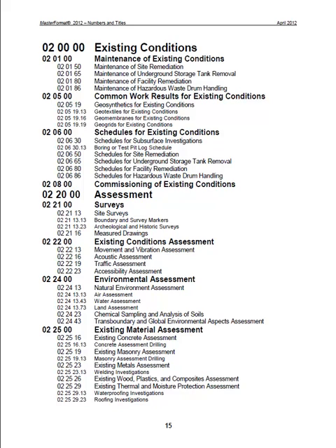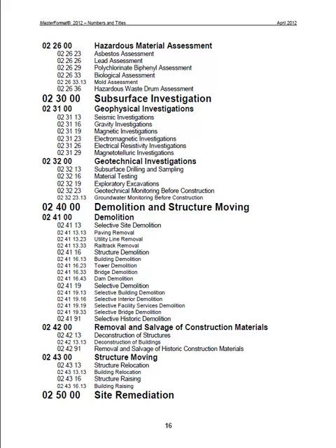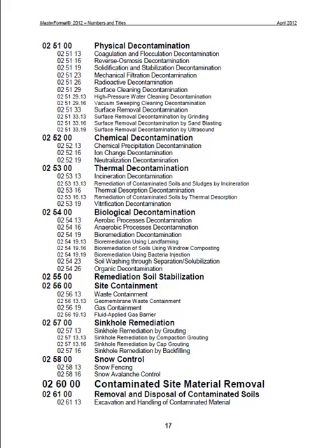Here's our Section 2, which is existing conditions. You see we have a lot of different things in the existing conditions. You may only have a few of these in your project, but they need to be listed in this type of organization with these numbers to determine that everything is being analyzed. Subsurface investigation can include seismic investigations. We have a specification section for seismic investigations. Anything that's for demolition and removal, including what you're going to do with that material when it's taken out, whether the owner takes it or you do.